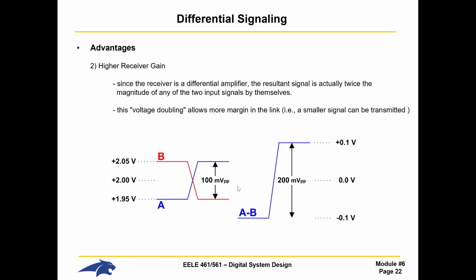When you look at differential signals, so stuff that's in USB or standards like low voltage differential signaling, LVDS, or even what's in your computer, PCI Express, serial ATA, any of these differential interfaces, the signal swings are really small. They are measured in the 100 millivolt range.